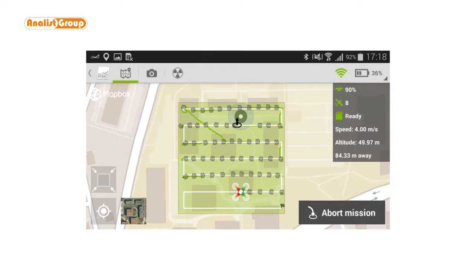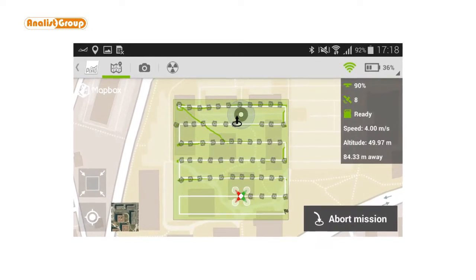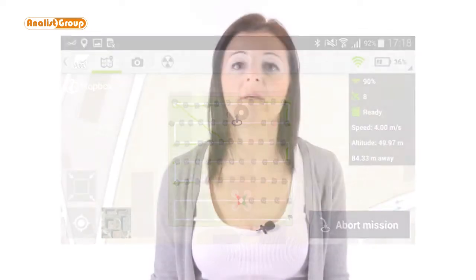Once we're on the scene, we need to plan our flight. What we do is we use an app where we follow a grid of the area we need to cover. The drone will automatically follow this area and take all the imagery necessary for our reconstruction.